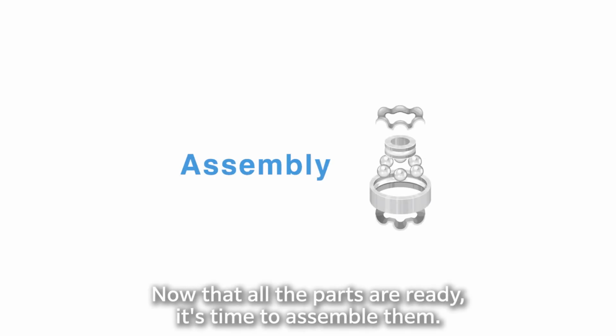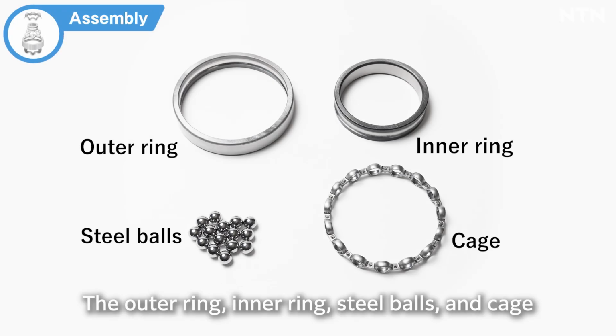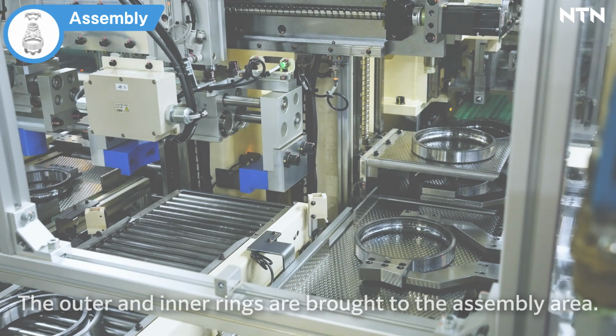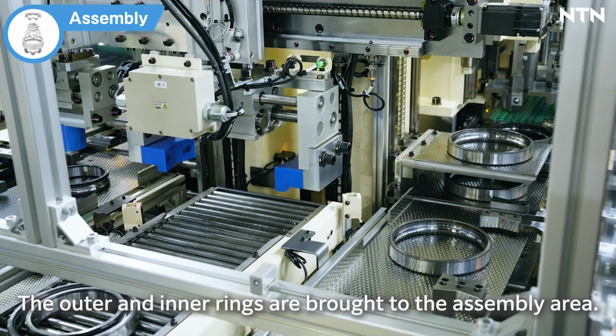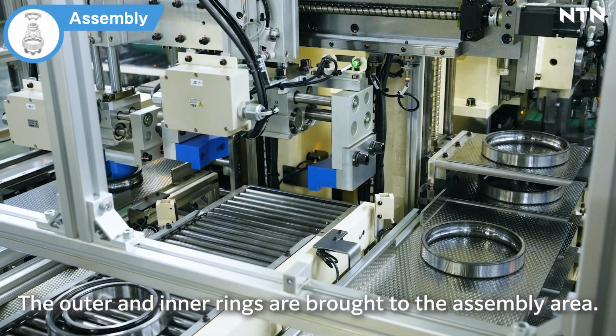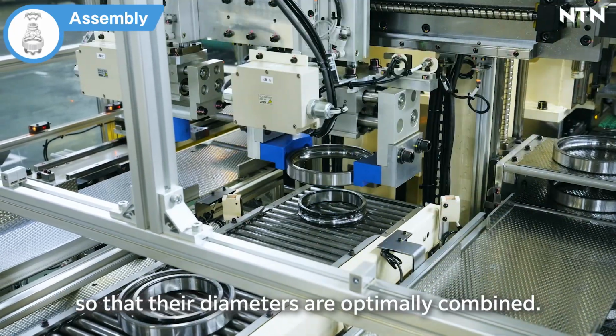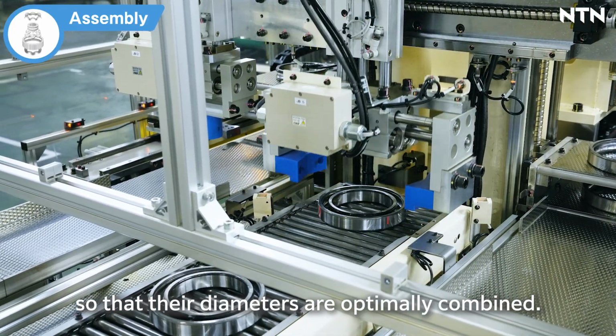Now that all the parts are ready, it's time to assemble them. The outer ring, inner ring, steel balls, and cage are assembled to form the bearing. The outer and inner rings are brought to the assembly area. The raceways of each ring are matched so that their diameters are optimally combined.